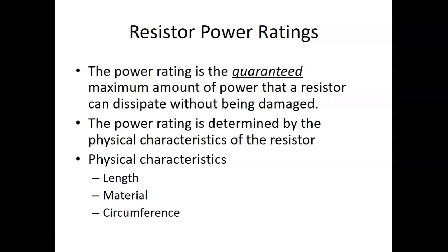Okay? So resistors are rated in two things, and you definitely want to write this in your notes because it's going to probably be a great question one day. Resistors are rated in two things. They are rated not only for what they can handle as far as resistance, but they are also rated for power. So a light bulb is rated for power. If you exceed that power, what does the light bulb do? It pops.